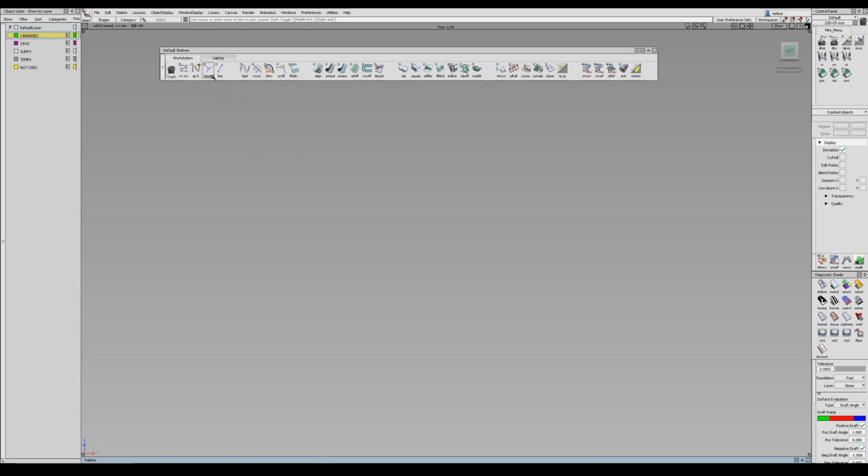So the first set is the curve tools, and I use very limited curves. I do not, nor do I recommend, using blend curves. That's probably a sin for some people, but I'm just not a fan of blend curves. They require a different paradigm to use them, and additional tools in, say, your marking menus or hotkeys. I think that's just not necessary. There are a lot of better workflows, I believe, outside of blend curves. So I mainly use just CV and edit point creation tools for curves.